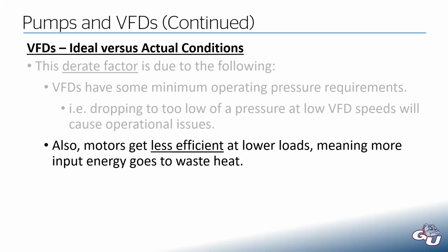Now we can still significantly reduce the operating power of the motor, but we are going to reduce the motor efficiency, meaning more of our energy going in ends up as waste heat. We can still see significant reductions in the total power, but it just won't be quite as good as that cubic relationship, just because we are going to drop efficiency.